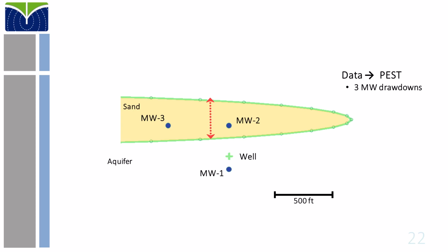I tried a couple of different layouts to add observation wells across the sand deposit in different spacings, but it did not seem to help. Then I placed a 4th observation well here in the aquifer, between the pumping well and the channel sands, and fairly close to one of the channel sands observation wells.